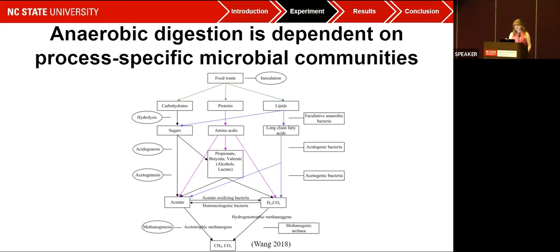So food waste can be used as a substrate in co-digestion. There have been multiple studies looking at monodigestion of food waste, but there are often process performance issues with digesting food waste on its own, due to low pH and lack of other nutrients that microbes need to perform these stages of anaerobic digestion. So using it as a co-substrate with other inoculums such as municipal solid waste, biosolids, and animal manure, we can counterbalance those issues and supply the other nutrients these microbes need. Mine specifically is looking at municipal solid waste. Using food waste in co-digestion can help eliminate some of these issues.